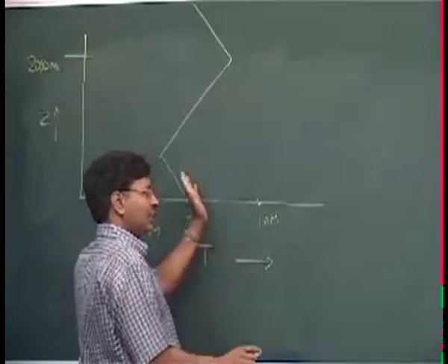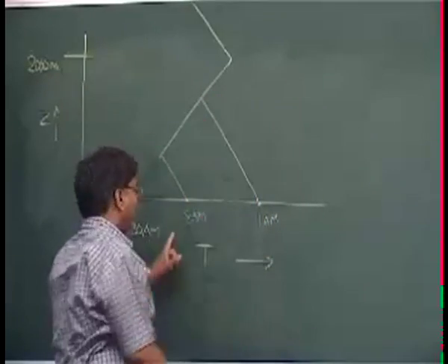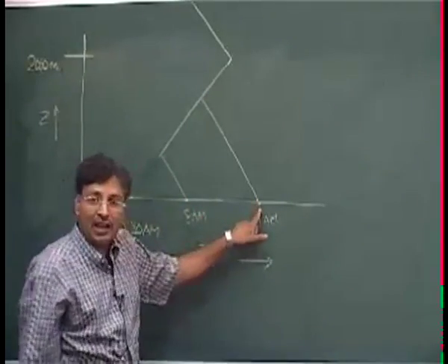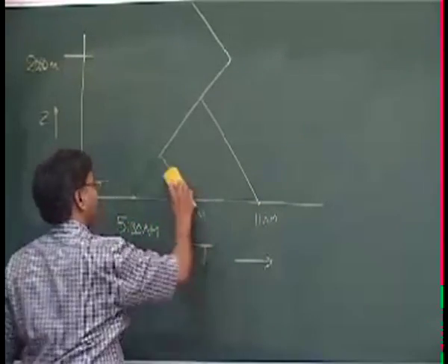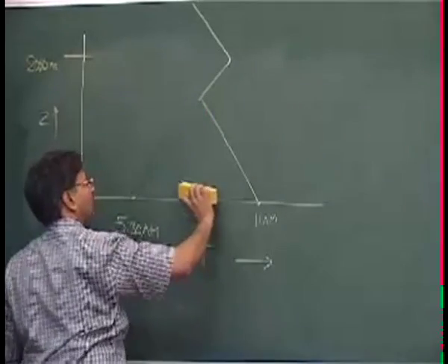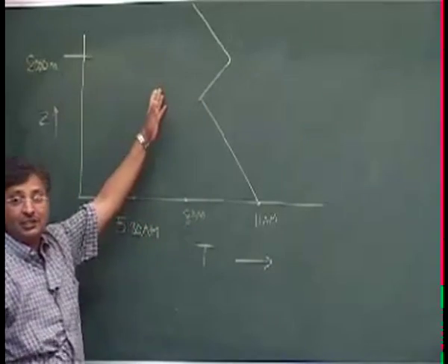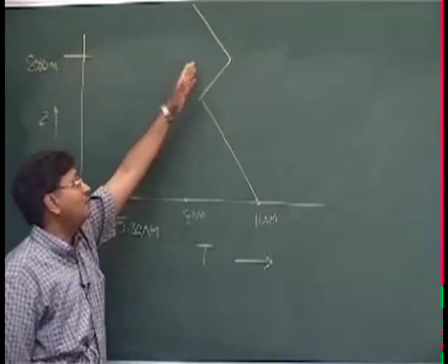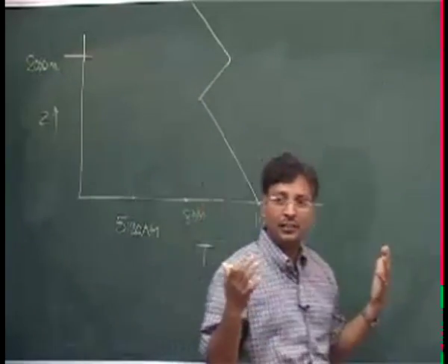There will be some slight change, but something shape will be, because by the time 11 o'clock temperature is even higher. And then you will see here at 11 o'clock the picture will look like this. So you see at the elevated levels, inversion is there, but at the ground level inversion is broken.